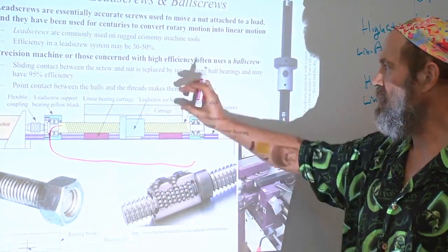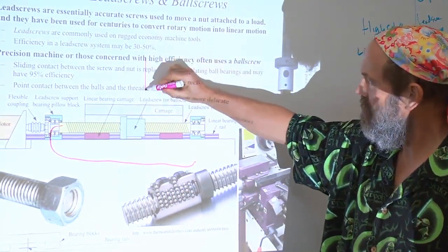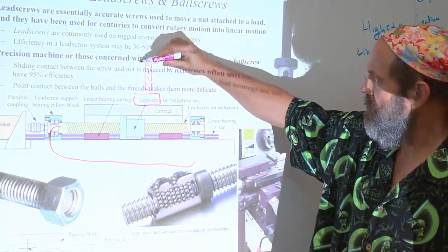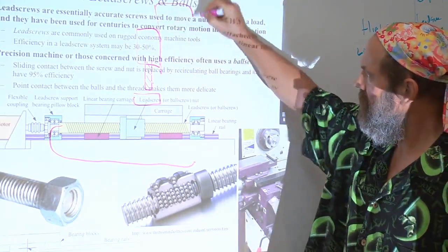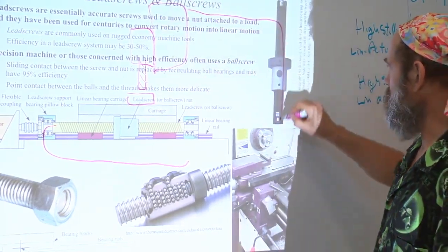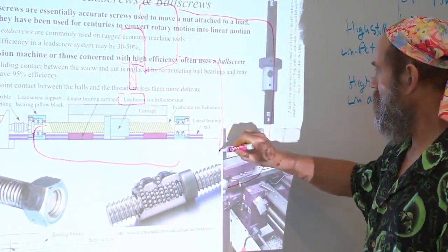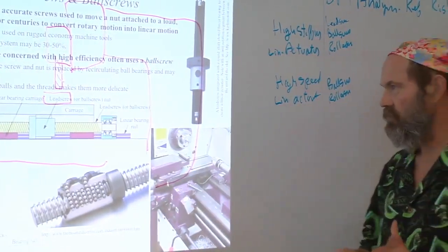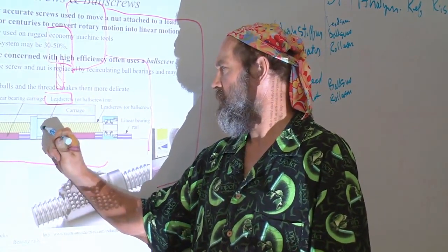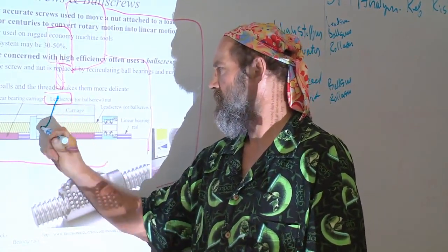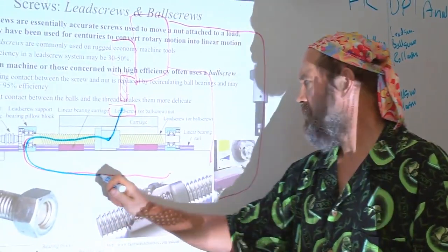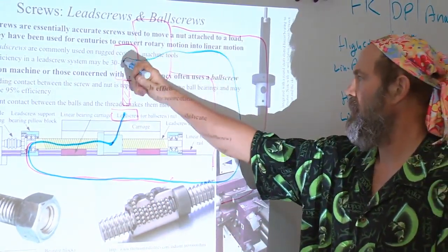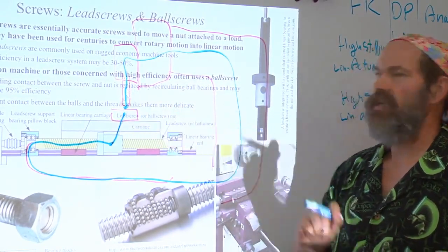Now somewhere on this carriage there's going to be a part, and here's your tool, for example, that's attached to a spindle head on the rest of the machine that comes around, mounted to the bed of the machine. This structural loop will go from the nut, table, all the way through the rest of the machine, through the head, through the tool, back to the beginning.